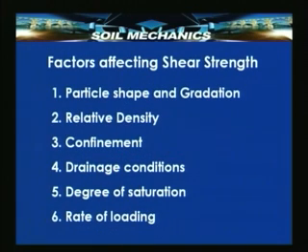Now, there are a number of factors other than this drainage which affect the shear strength of a soil. Primarily, we can identify 6 such factors. These 6 factors are listed in front of you here. The type of the particles are responsible for the kind of shear resistance that can be mobilized between the particles when they experience the interlocking pressure or the intergranular stresses.